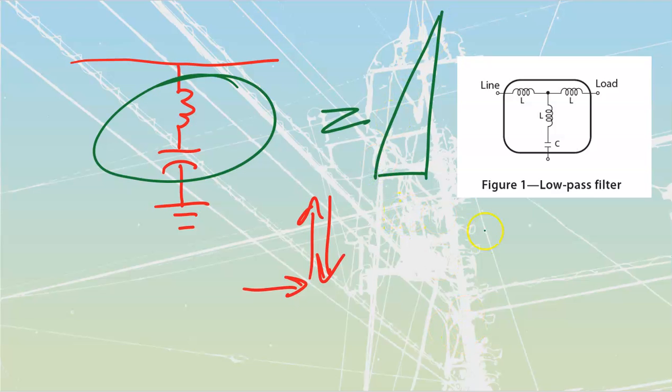But by the time I take this up to 180 hertz, if I'm going to filter out the third order, all I'm really going to be left with is a tiny little bit of Z and maybe a tiny bit of XL or XC off of that. Therefore, it's going to have a very low Z. The actual physical resistance of the copper is the only thing that stays in there. And so it's going to dissipate those harmonic currents themselves.